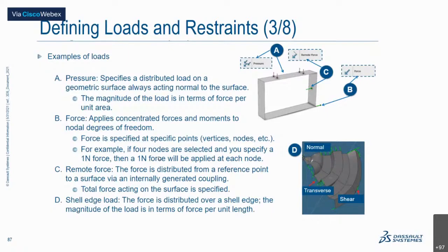While for force, you can either select a vertex, a node, or a common center point in the given model. So that is up to the user as to where the force is to be applied. And the unit for force that is being followed is Newton here.